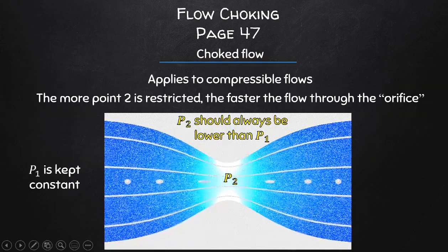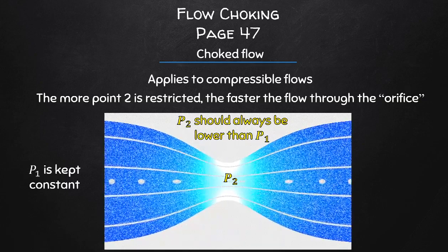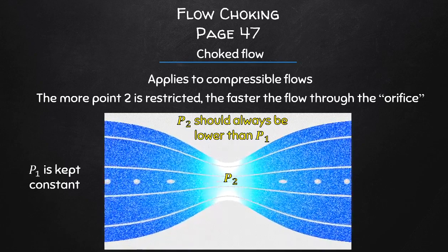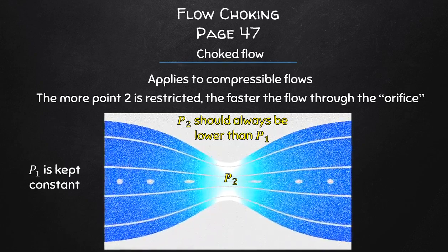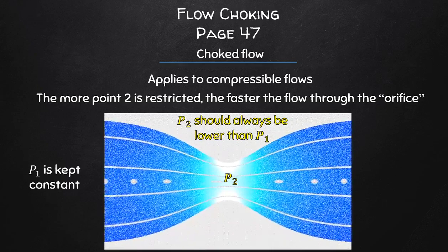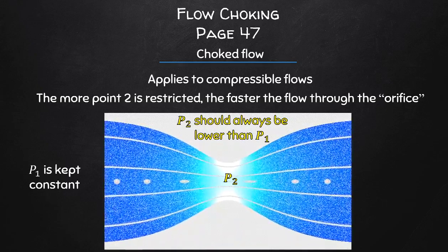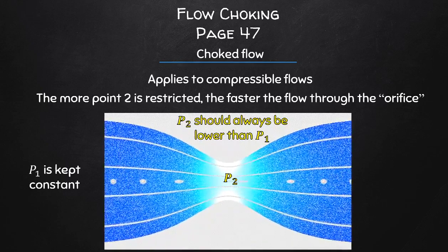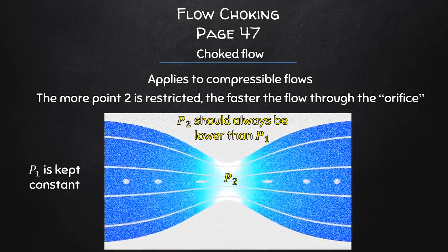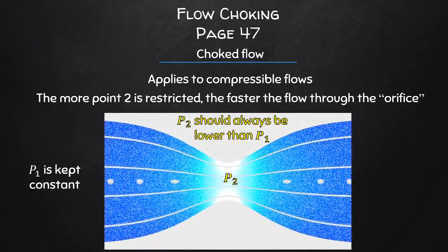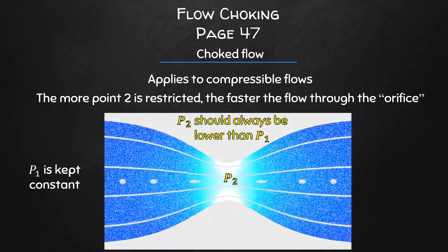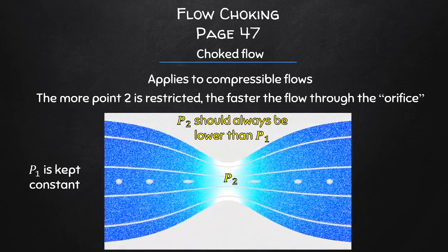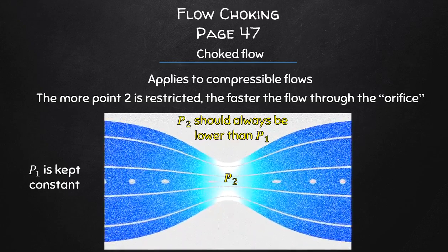Now, for changes in diameter, the conservation of mass must always hold true. And at the same time, the pressure that is being measured drops considerably at the reduced diameter as shown. So if we had to put in a manometer across the two diameters, then we would measure P2 as being smaller. But now, how can you explain this?